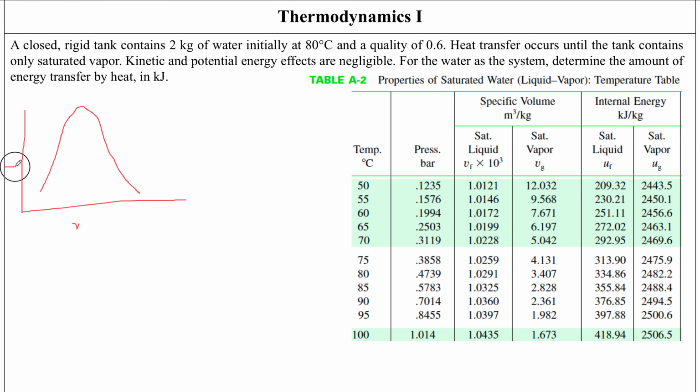It says specific volume on the x-axis, temperature on the y-axis, and what's happening is that you've got constant pressure lines on this TV diagram. For example, the pressure remains constant here. I'm just making isobars here, so let's say it's 10 megapascals over here. So it's going to be 10 megapascals throughout from this point until this point.